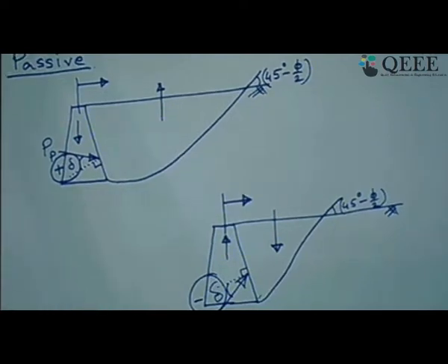Yesterday, if you remember, I was mentioning that for retaining wall design mostly we consider active earth pressure. I have explained why we don't consider passive earth pressure below the dredge line, because of the scouring effect, or not having the full state of passive condition mobilized. Those are the reasons. I said the application of passive earth pressure, though it is minimum for the design of retaining walls as such, has huge application in other areas of geotechnical engineering.